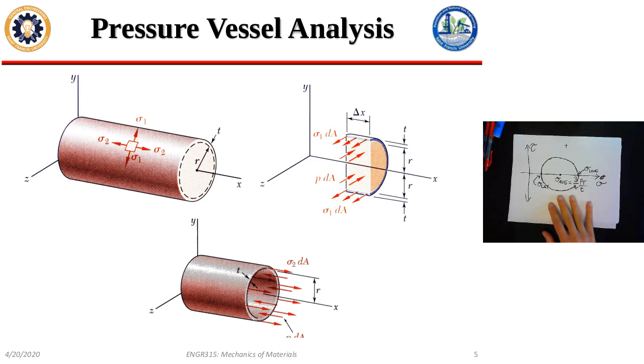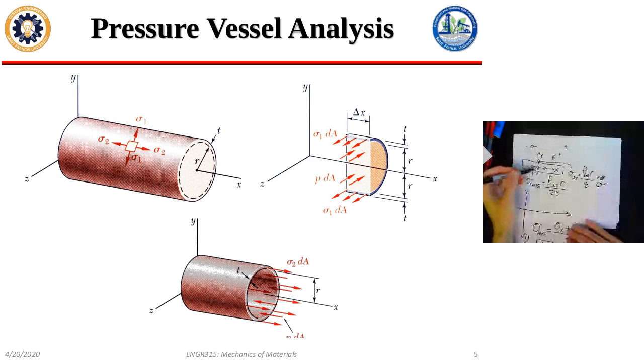Okay, so this gets fun then. This is Mohr's circle for that 2D stress element. But what you might be thinking is, wait a second, it's not a 2D thing, right? If I go in with a welding torch and cut that stress element out of the hull of the pressure vessel, it's going to be a 3D thing.